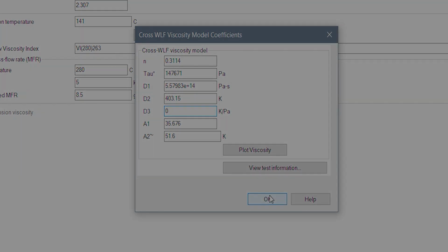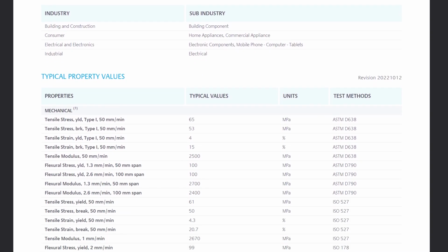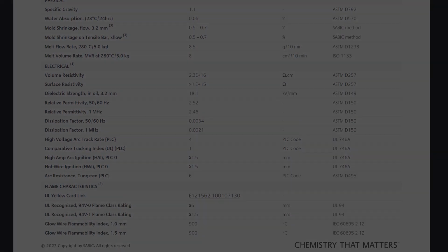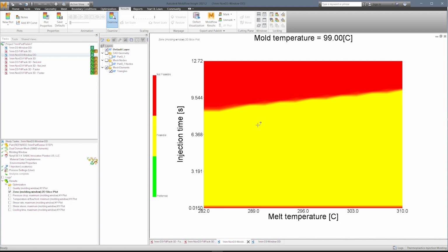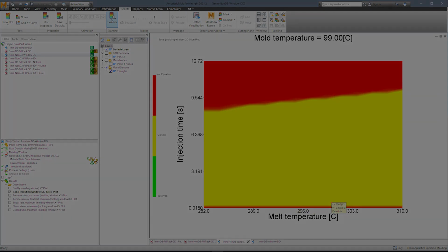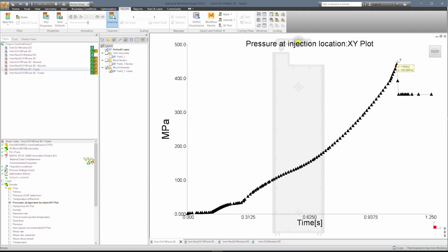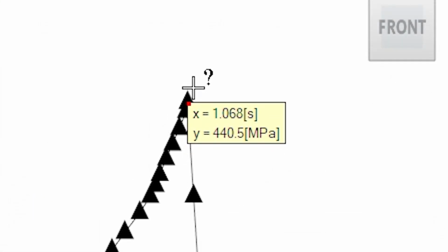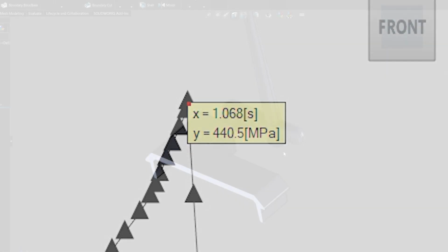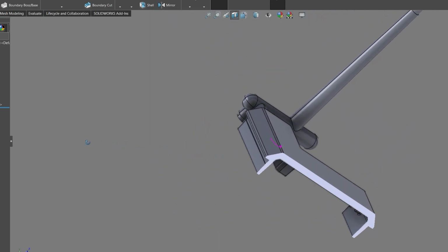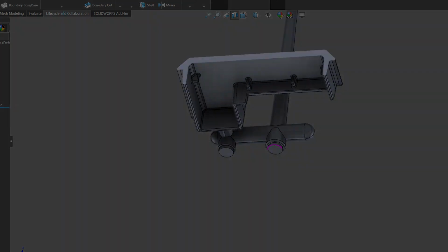The material selected for the project was SABIC's Noryl SE1X, which is a blend of polyphenylene ether and polystyrene. A preliminary Moldflow simulation was made to establish a likely processing window for the real-world process, as there was very limited material available for this project. These simulations revealed that the pressures were expected to be very high for the testing, and as such, the planned mold insert to create 1 mm thick parts was exchanged for a 2.5 mm part insert.